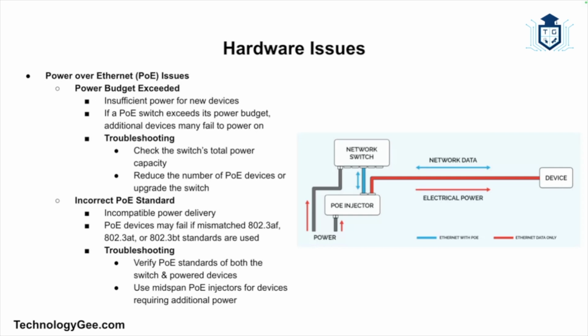And then we have the incorrect standard. So using incompatible PoE standards can cause device failures. And to fix this, you want to verify PoE standards on both the switch and powered devices, and then you want to use mid-span injectors for additional power needs.